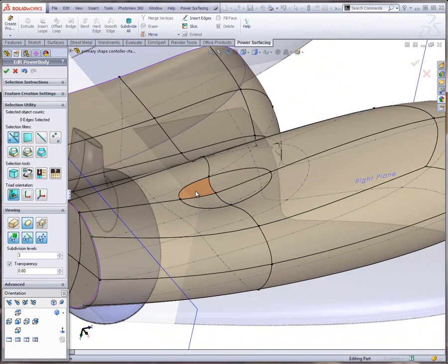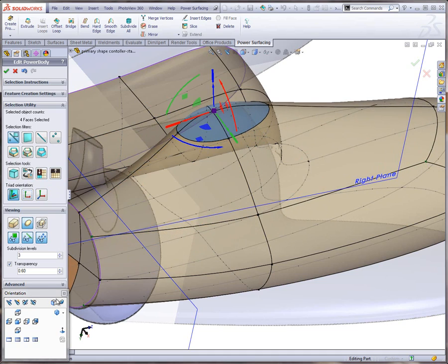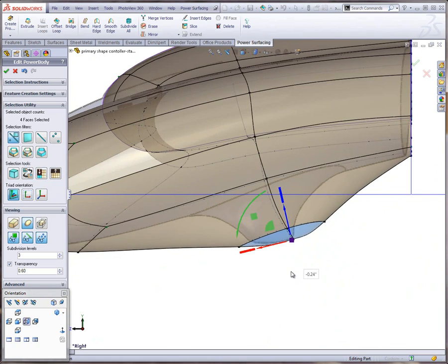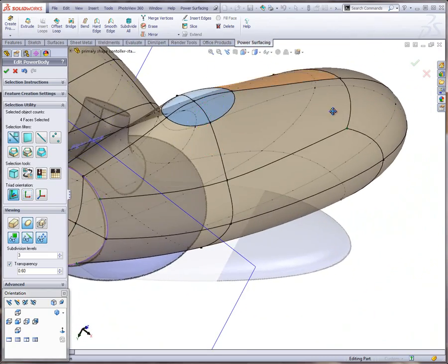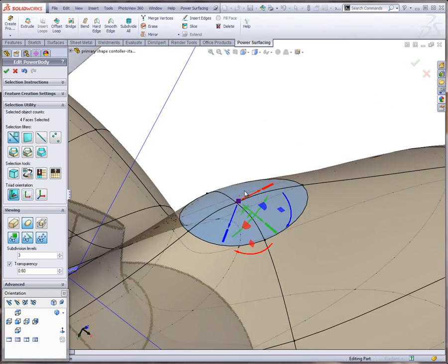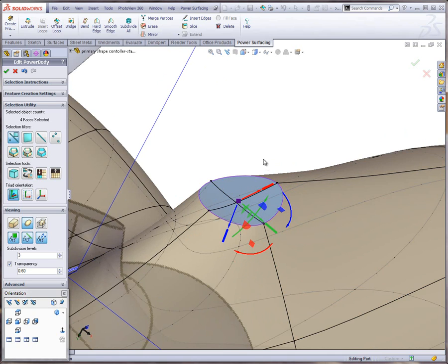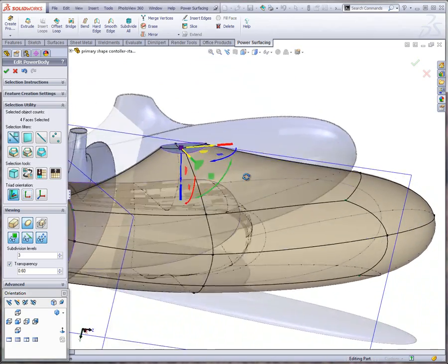Okay? So now I can grab all 4 of these, and let me just go on our global axis, just pull, maybe I'll go local, and just pull out, okay, to match something close to that height. Okay? So while you have that selected, then you can right-click and say, add a crease, okay, which is weighting it 100% to an edge.